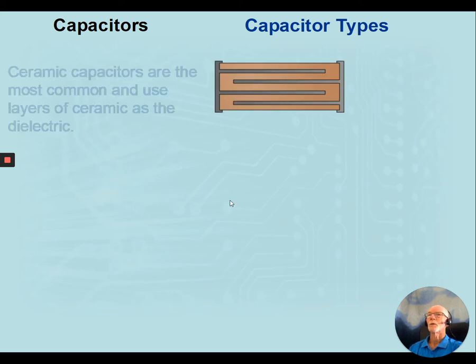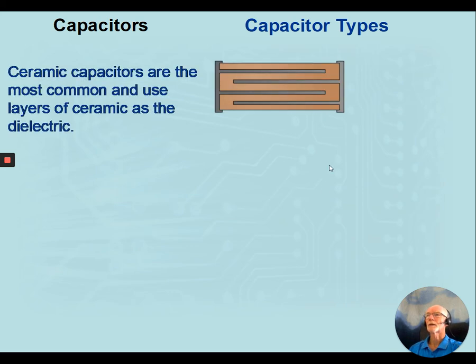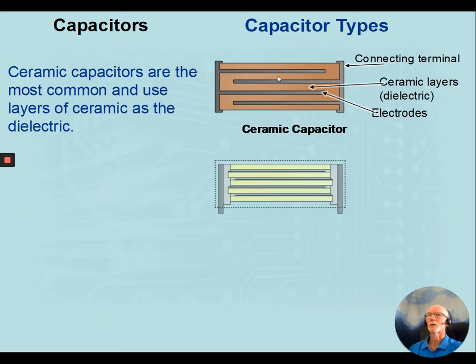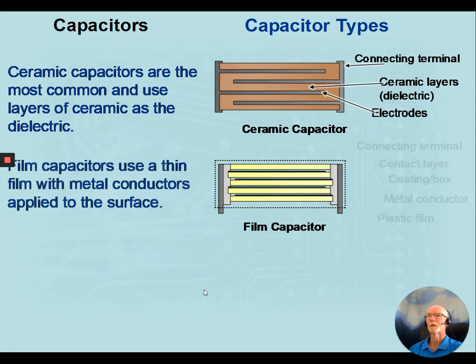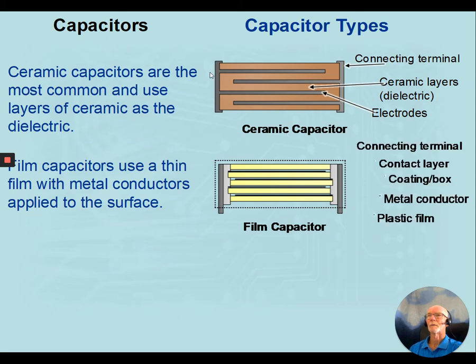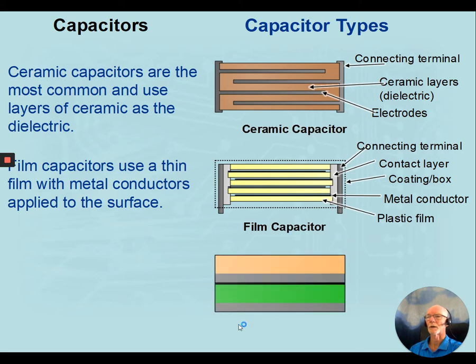The way we can increase the value of capacitance is by having multiple plates inside the one capacitor with dielectric interleaved between the plates. So for example, in a ceramic capacitor, one side would be connected to one of the output legs, the other side to the other output leg, and so we have multiple areas for our capacitance to go.